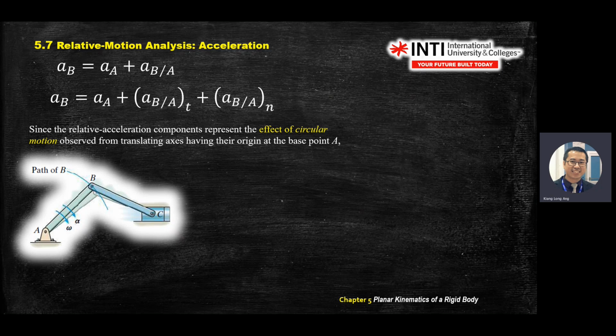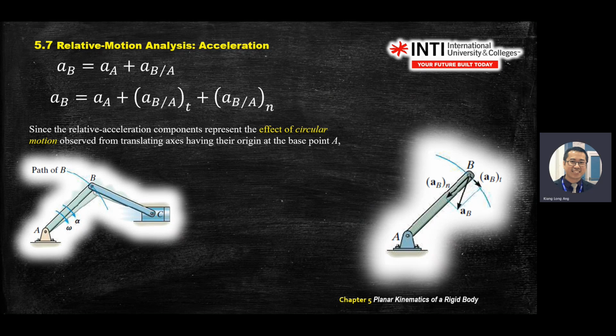Right. Now, this diagram, you should be able to draw the motion diagram or kinetic diagram, right? So you look at AB first. For AB, you draw the kinetic diagram. You focus on this arm only. So B rotates clockwise. You have a tangent acceleration direction and a normal direction acceleration. You square tangent plus square normal, square root, you get the resultant.